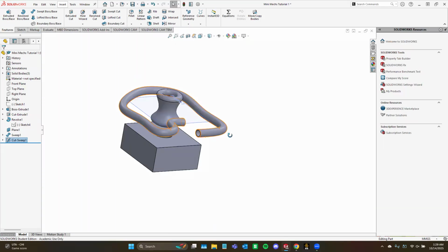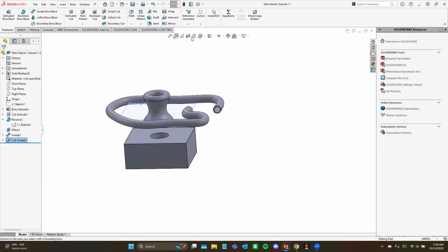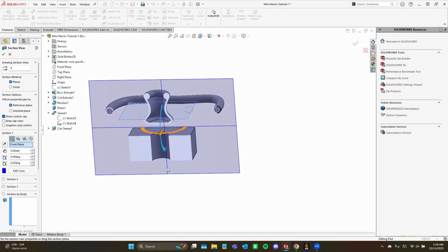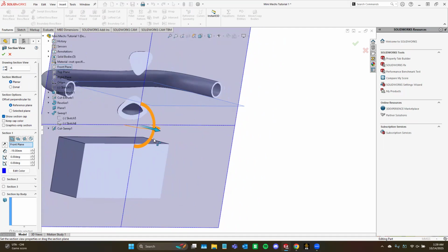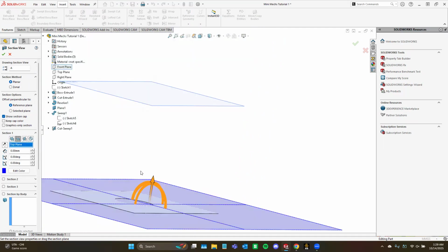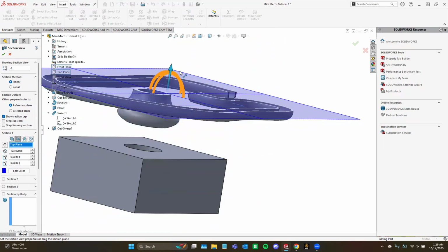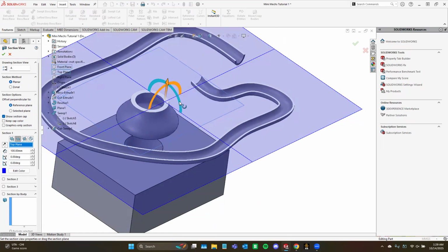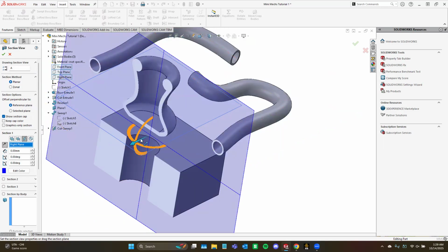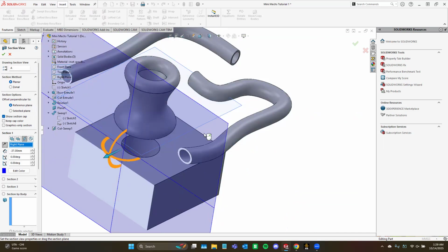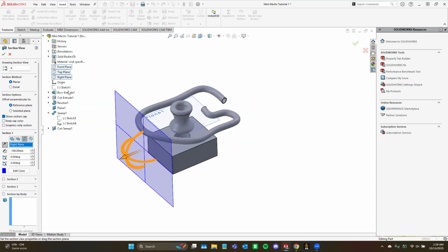the whole thing. And to prove it, we're going to use something called a section view, which should be this button right here. And it basically just shows you a cut off section of your part. So as you can see, it's already doing that for us. You can move it. You can change its direction, have it come from above. This looks pretty cool. Low water slide. But yeah, you guys can see it's completely hollowed out due to the swept cut that we did.